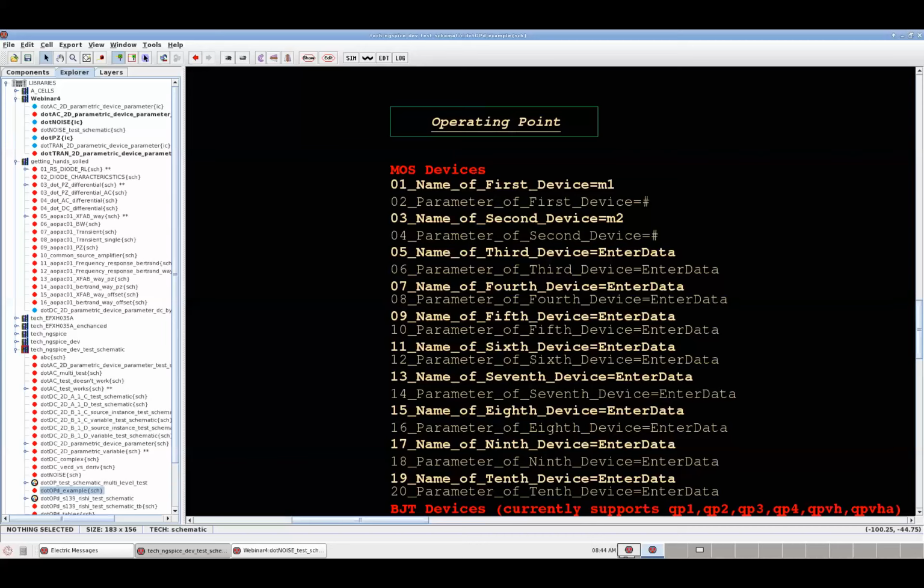So this is the flow. You first do .transient, then you use .measure, saying that when the envelope of the settling reaches 10% of your desired value,